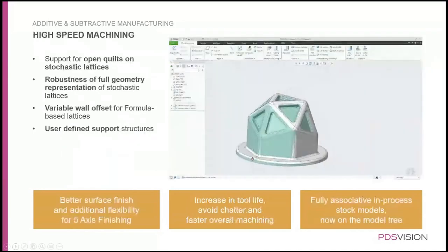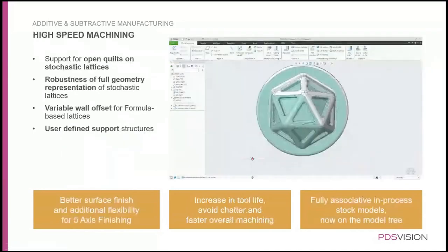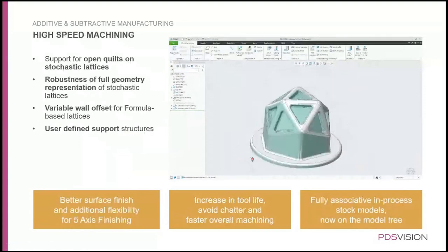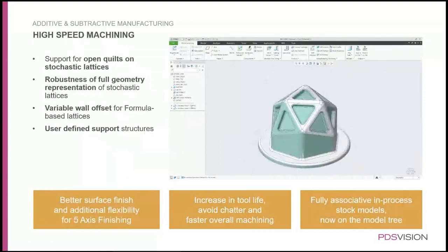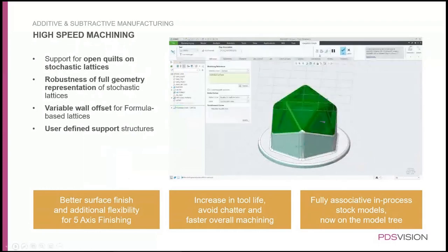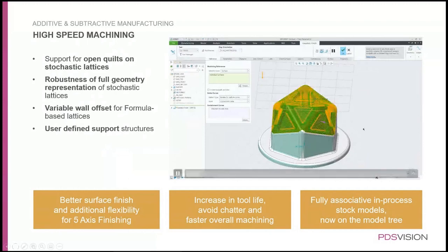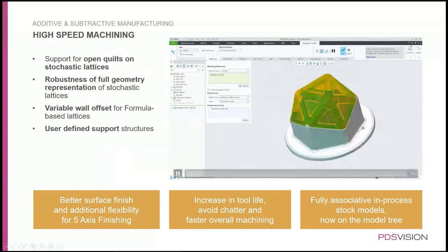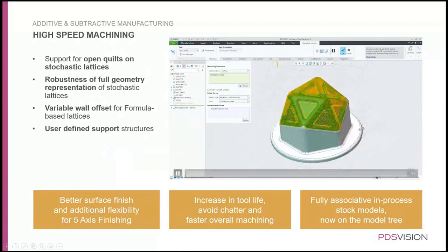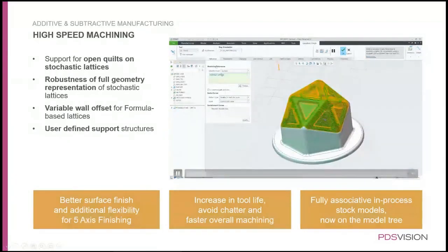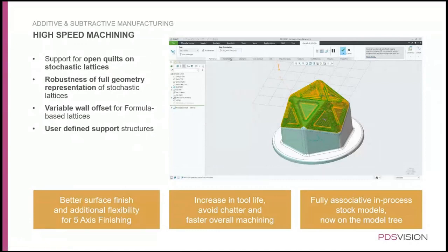Then with high-speed milling, in one of the last slides, what we have here is the capabilities of... okay, it seems my texts are still quite funny. The texts are for the previous slides, so let's see. The idea is that we can do this kind of geodesic machining path, especially with 5-axis milling. It's getting a bit complex to make a constant step rate, a final milling path here, which then doesn't collide or gouge the piece at all.